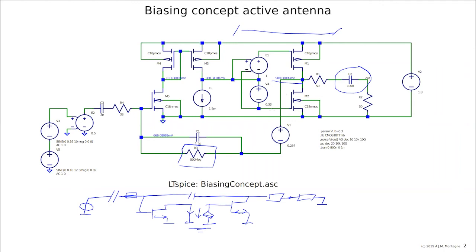And you see it is tuned. And since this gate voltage doesn't need to be 900 millivolt, I need a difference. And this voltage, this level shift, is setting this difference.